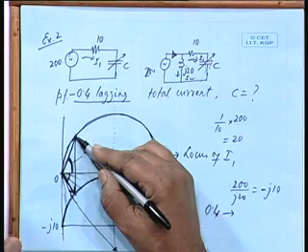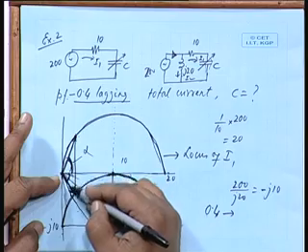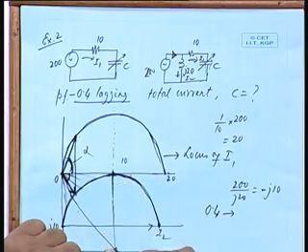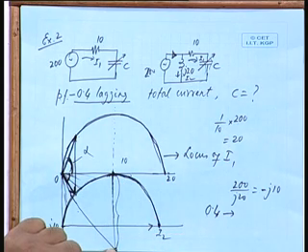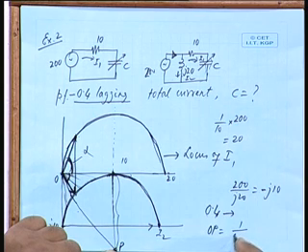So, this was the location of I, corresponding to y, corresponding to admittance, this was the angle. Corresponding to z, it will be minus alpha. So, at minus alpha you draw a line that will give you the corresponding reactance, it is 10 plus jx. Once you get this height, that is 1 by omega c. Suppose this is P, then OP is 1 by omega c. So, you know the desired C, is that all right.